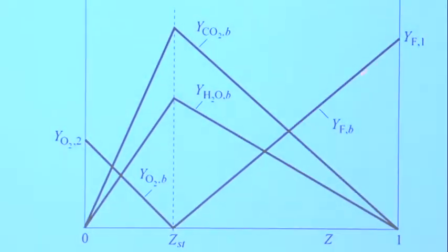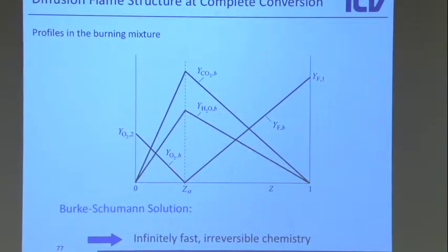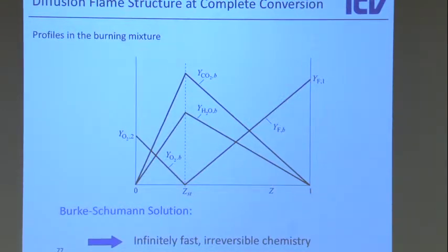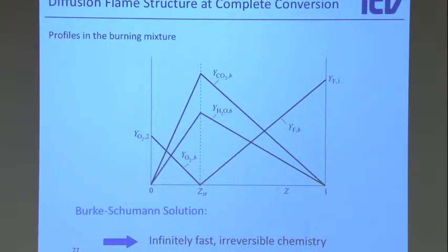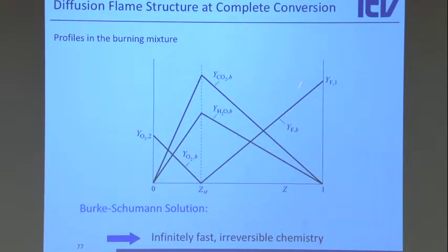So that's the flame sheet model. And here you see there's no curvature. It means there's no chemistry going on here or here. And the reason why is that what happens here is just transport. Why does this go to zero? Because here I consume it. So this is a diffusive flux of fuel from the fuel stream into the reaction zone. Okay, diffusive flux. And so this here is all diffusion. And because mixture fraction and species diffuse in basically the same way, they have a linear relationship.